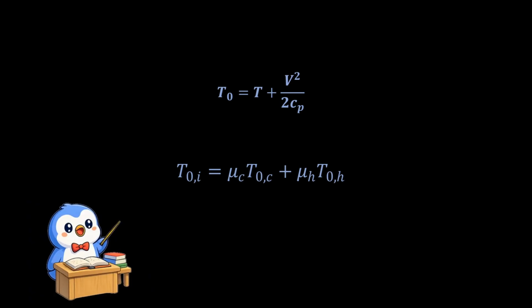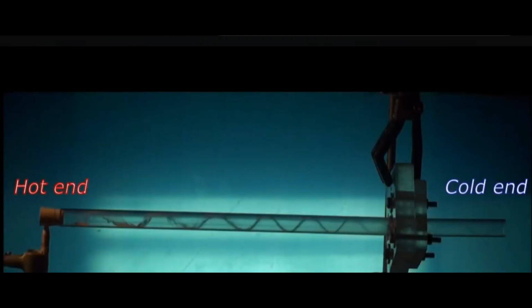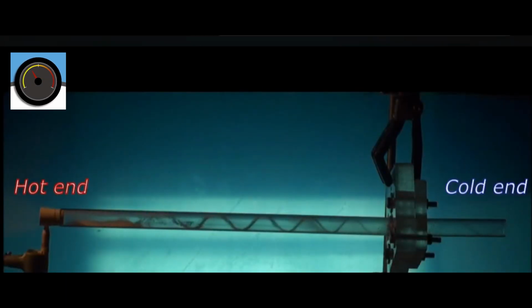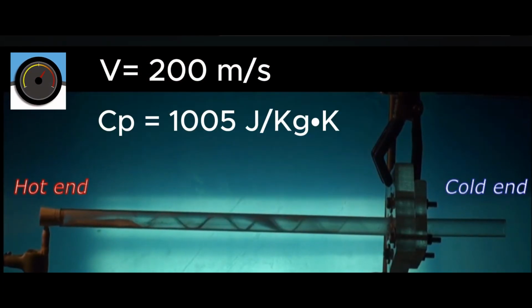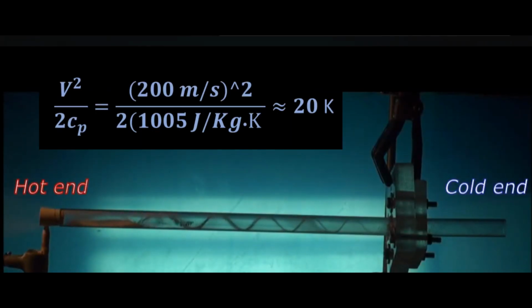That part matters. For example, suppose the air inside the tube is swirling at about 200 meters per second. For air, the specific heat is about 1005 joules per kilogram Kelvin. If we express that kinetic energy in temperature units, we get that the motion of the air alone can account for a temperature equivalent contribution of about 20 Kelvin. It helps explain why the energy balance in a vortex tube has to include both thermal effects and flow motion, not just temperature by itself.